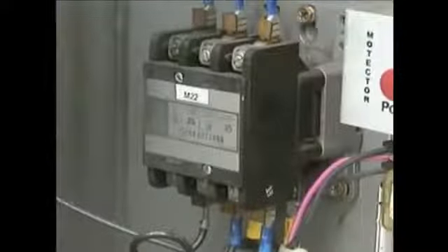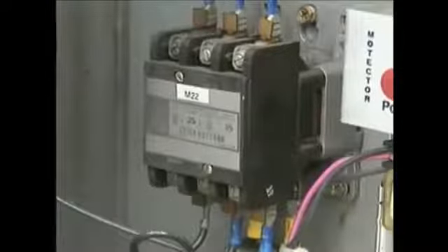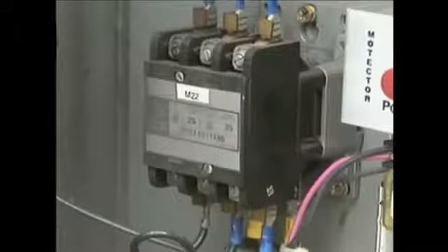One advantage of using a contactor in an AC motor controller is that it can be energized from a remote location using a voltage that is lower than the motor's operating voltage. The power circuit is energized or de-energized by devices operated by the lower voltage control circuit. This protects personnel from high voltage hazards when they start and stop high voltage motors.